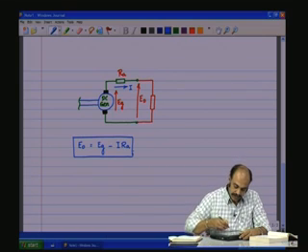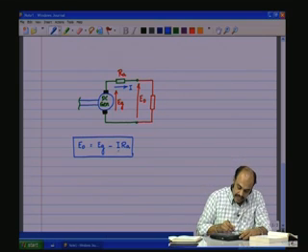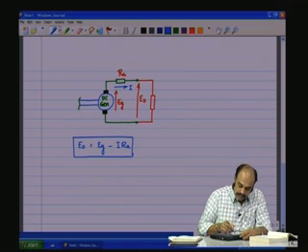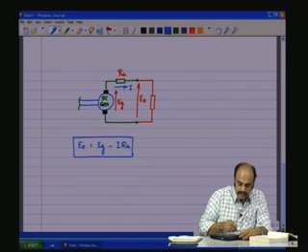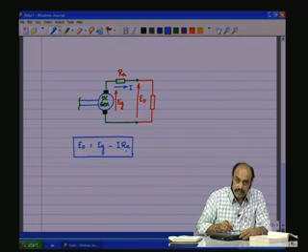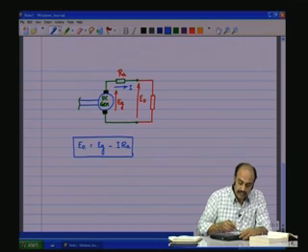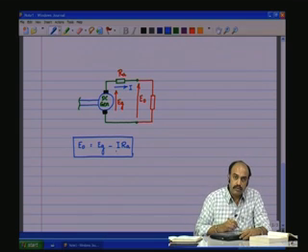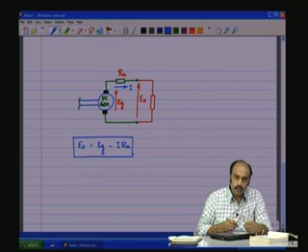and this is the equation which gives you the load regulation portion. As the current here increases, and why should the current increase? If the load here increases, the current here increases, and as the current increases, the I RA drop increases, thereby the effective voltage across the terminals of the generator will be Eg minus I RA, which will be less than Eg by the amount of the drop across the series resistance RA, which is the armature winding resistance.